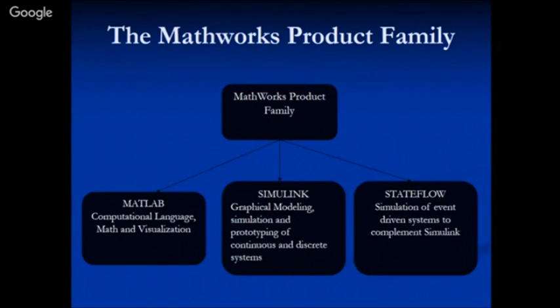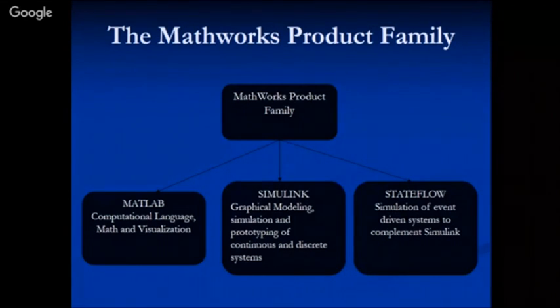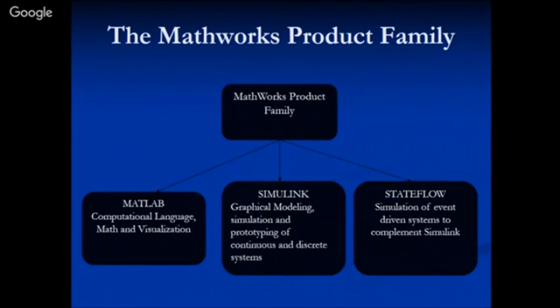So this state flow is a very powerful thing. Whenever you want to represent a system, how will you represent it? You either have a transfer function of it or a state space model of it. The advantage of the state space model is that intermediate analysis can be done with it. In the case of a transfer function, there is only the input-output relation. What is a transfer function? It is the Laplace transform of output over Laplace transform of input.